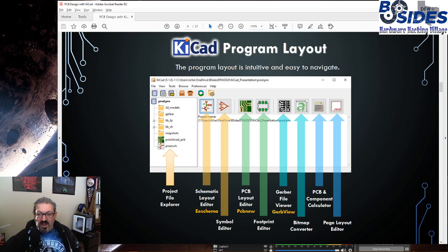other graphics for use on like a silk screen layer, or even if you're doing like a copper fill area on your design, and you want to use like an art type program like Adobe Illustrator to actually do the fine artwork for how you want that shape defined, you can then export that as a bitmap and import it here, and it will import it in the footprint format that the PCB Layout Editor will read in as a footprint.